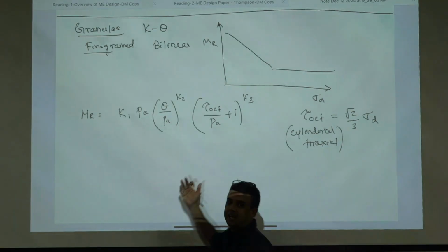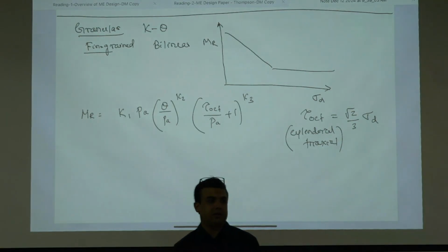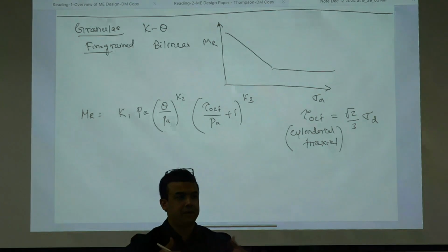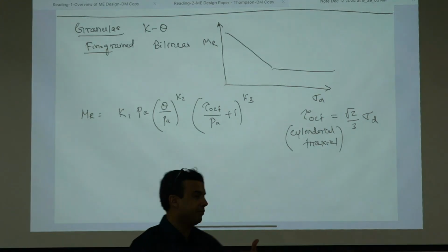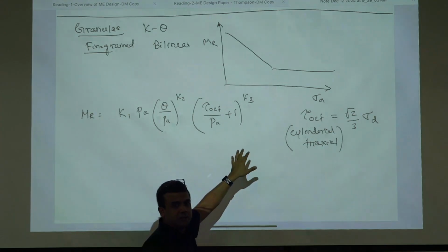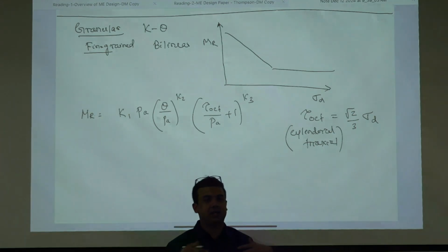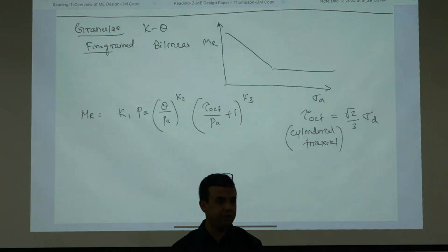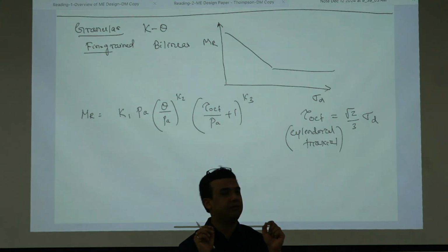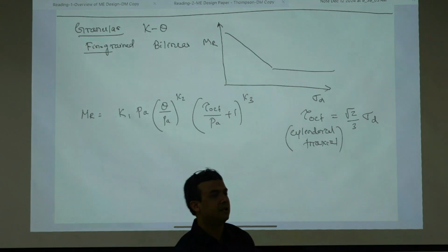For aggregate materials, the K2 stress portion actually represents the stress hardening properties. For subgrade soils, it is the K3 portion that actually represents the stress softening. So what can you say about the sign, SIGN, not SINE, of K2 and K3?